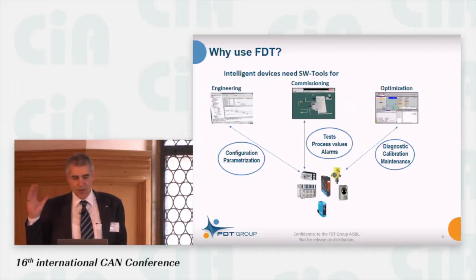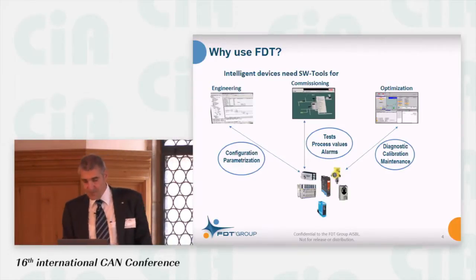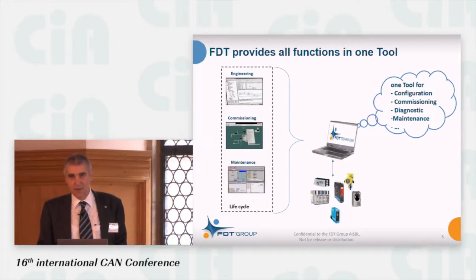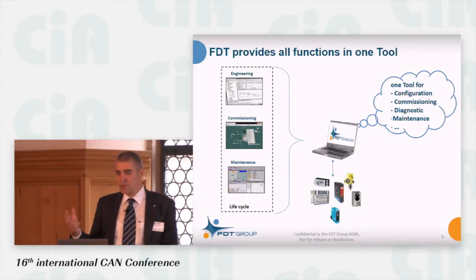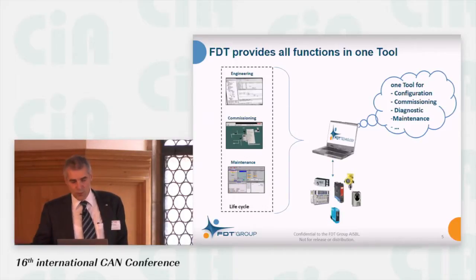And you have a lot of these tools today, standalone single tools for each device and even each field bus. And with FDT, we are able to provide all these functions in one tool, so you can have one tool where you configure all the different devices, maintain them and commission them, whatever you need to do with your device.